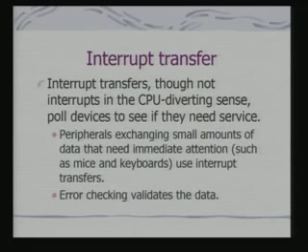The interrupt transfers are not really associated with interrupting the CPU. Basically, the whole objective of the interrupt transfer is to transfer small amounts of data, small packets of data. So peripherals which are exchanging small amount of data that need immediate attention, such as mouse as well as keyboards, use interrupt transfers.